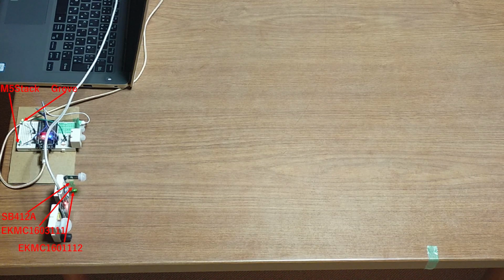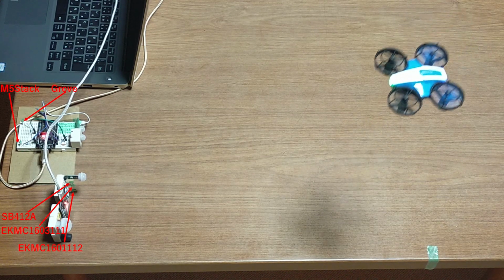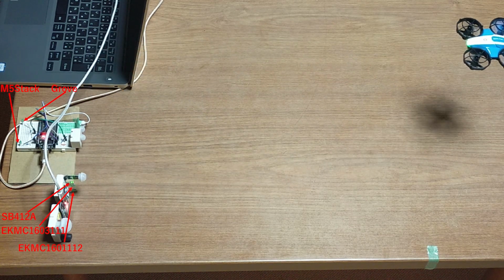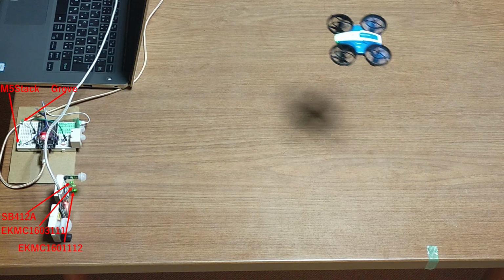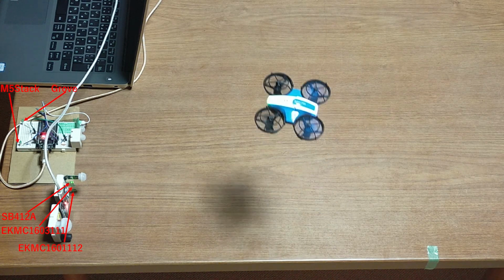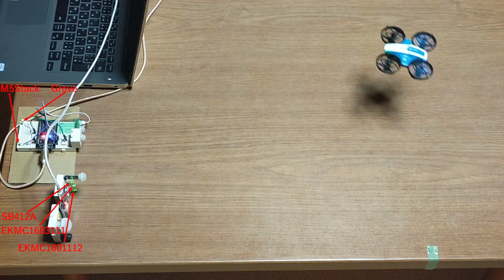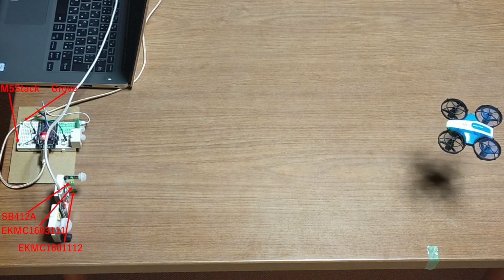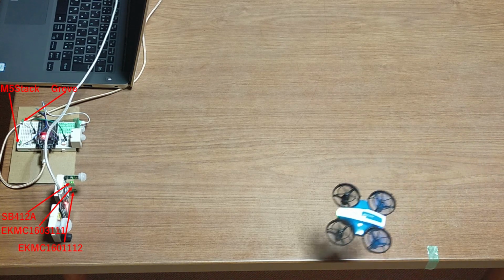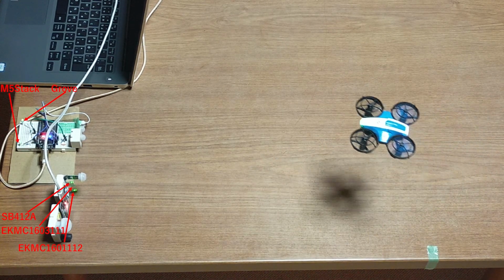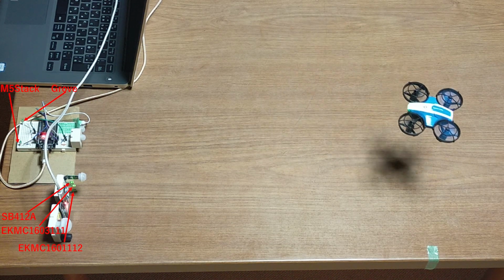I think Grove and Panasonic had slightly better sensitivity, but it fluctuated a little and there was no big difference, so I generally set it to 50 centimeters. Since the temperature difference between the room temperature and the drone is about the same, it is difficult to detect, and the Fresnel lens widens the field of view, so I think it will be difficult to react to small objects. Also, I think that the comparator deliberately does not make judgments unless there is a certain amount of change, so as not to cause false detections even if the plants are swayed by the wind.